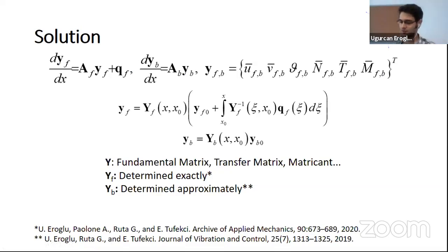As for imperfection, I think it will have more impact when the arch is shallow, because then there might be the possibility of symmetric loss of stability and skew-symmetric loss of stability. And at that time, when the arch is shallow enough, there might be the impact of imperfection. We haven't dealt with that, but when the arch is quite shallow, then the imperfection will play a greater role, obviously.